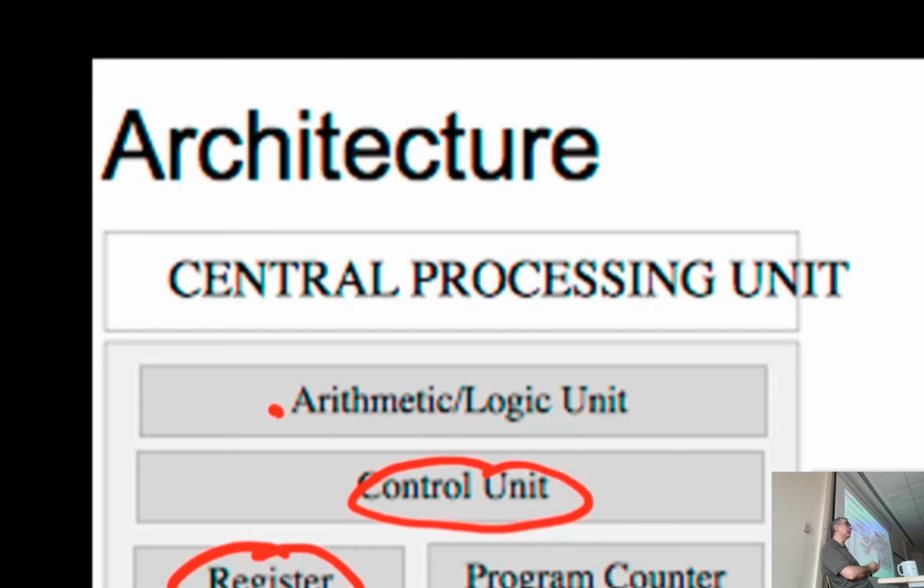After one turn, it will be the next automatically, unless I say go to somewhere else, based on the condition of some internal register, which is the implementation of an if statement. If this is equal to that, then go to here. That will be done by checking a variable and jumping accordingly.